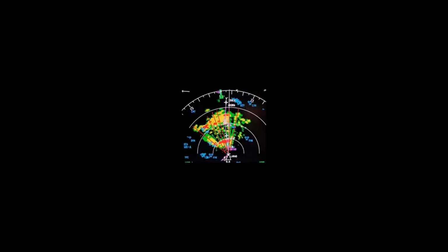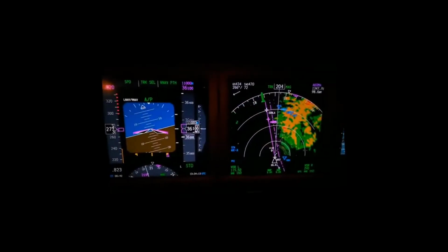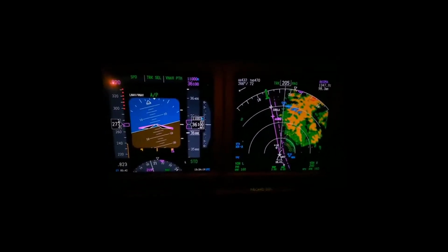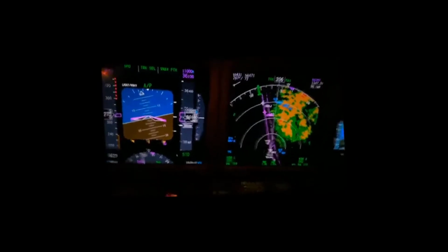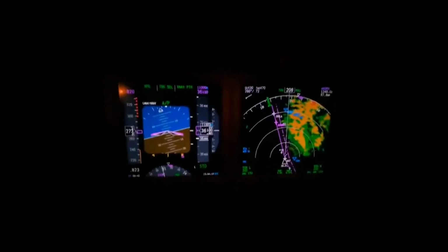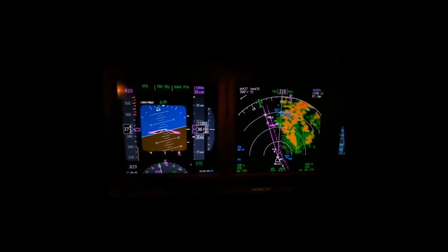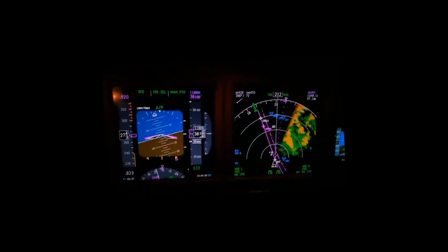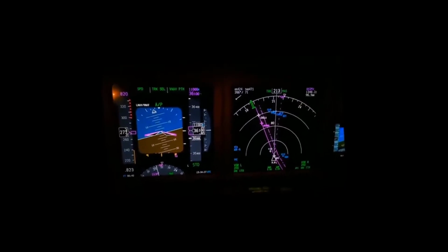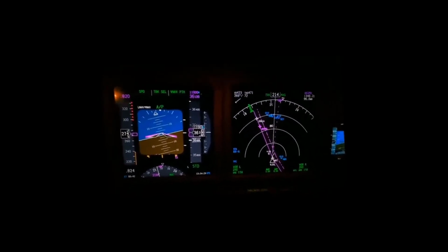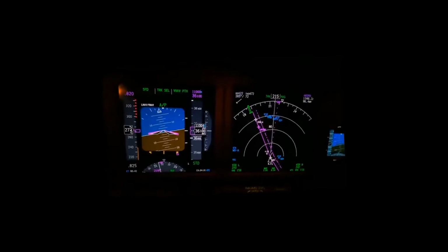Radar systems come into our shop with write-ups regarding spoking as the reason for removal off the aircraft. The most common type of radar spoking appears on the display as a pie-shaped patch only when there's weather. Spoking is a general term used when a radar system fails. You can determine which part of the system is causing the problem based on what appears on the radar display.